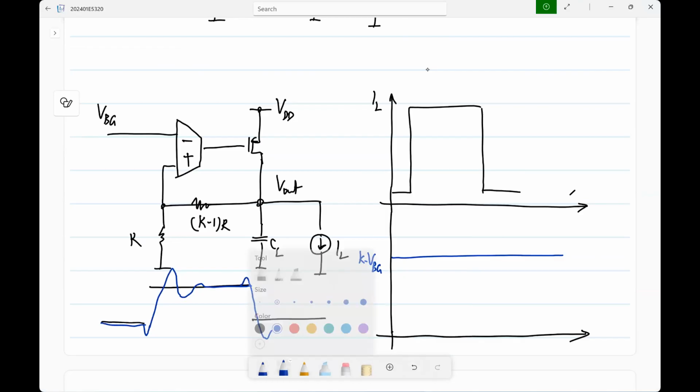So you expect this to dip down like that, right? Initially, it will jump down. Okay. In fact, if the capacitor is like this, all this current will just come out of the capacitor. It will dip down some. Then what happens after that? It will rise. Where will the current come from?